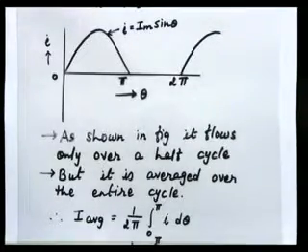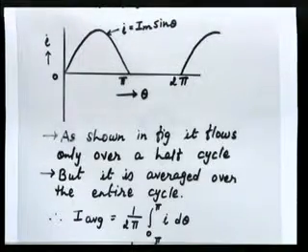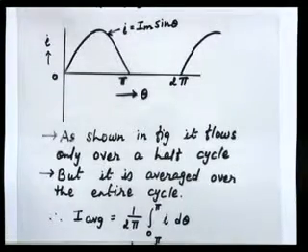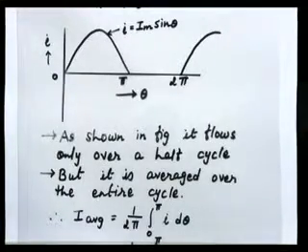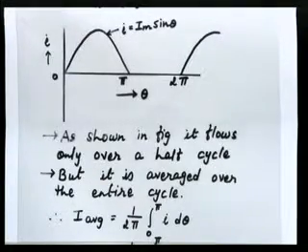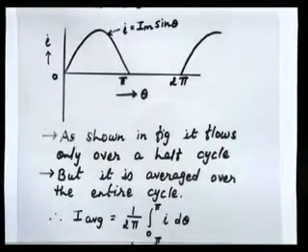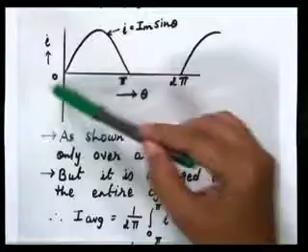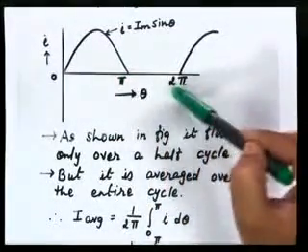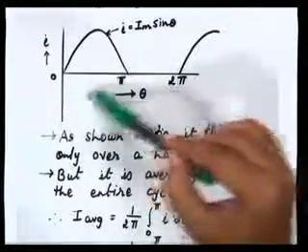Then if you have to find the average, it is equal to 1 plus 2 plus 3 plus 0 plus 0 divided by 5, because the number of matches played by this player is 5, so you have to consider the number of matches as 5, although in 2 matches he scored a 0 value. The same funda you can apply for a half wave rectifier. In the half wave rectifier, between 0 to pi you have some values, and pi to 2 pi you have 0 values. So whenever you find the average, you have to consider the whole cycle.